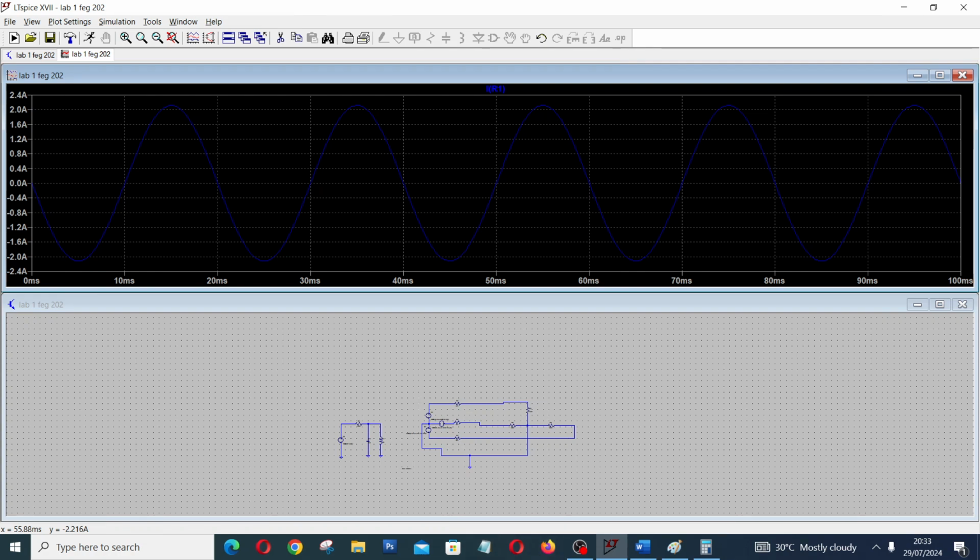It is when the voltage is getting low. A sinusoidal waveform changes periodically. So during the positive half cycle, the capacitor will charge. When the cycle is repeating and the voltage is going down, once the voltage at the supply is lower than the voltage of the capacitor, the capacitor will begin to supply voltage to the system. So it is that advantage we make use of in power factor correction. We're going to see that in the next video.